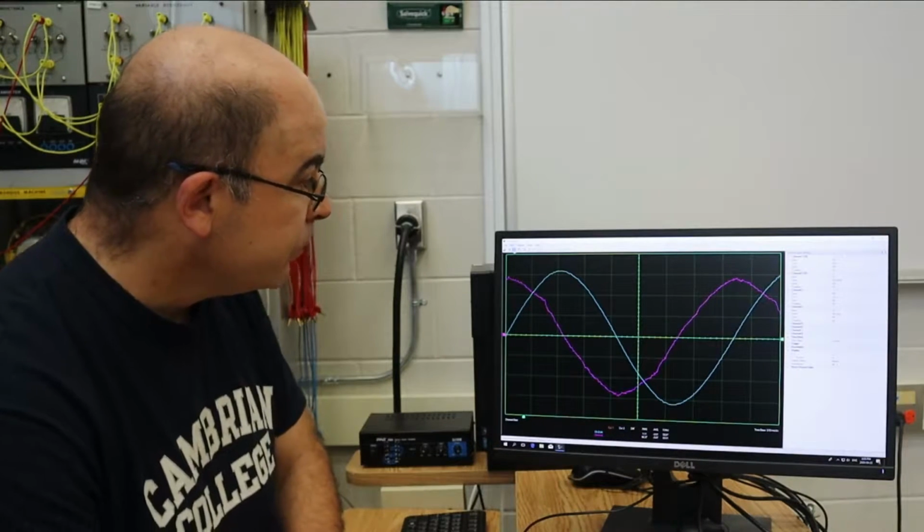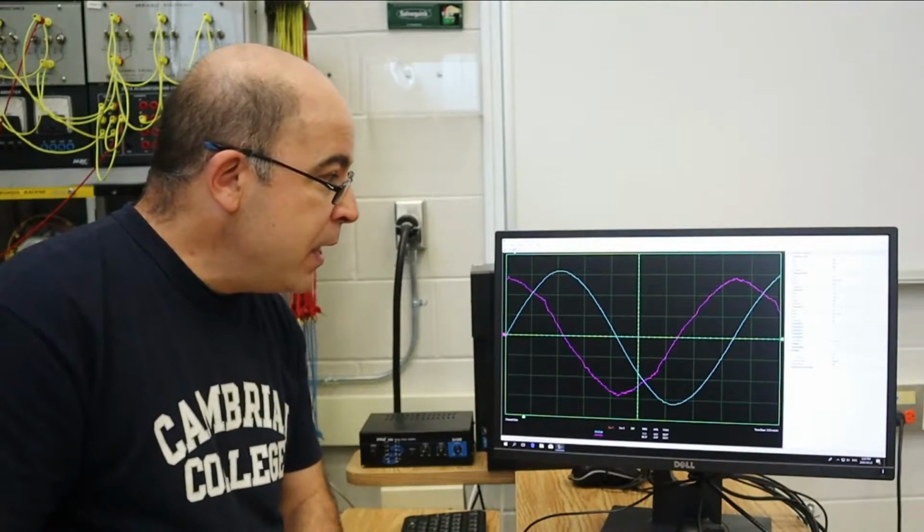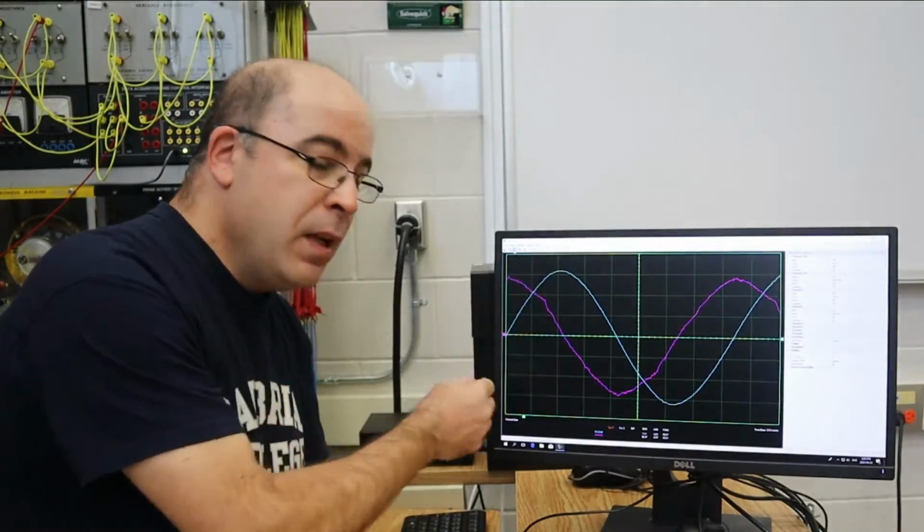Well, that's pretty good. So what do we see? According to our theory, there should be about 90 degrees of phase angle difference between the current waveform and the voltage waveform. Now, in a series circuit, the current waveform is stationary. Because of that fact, we have to say, because this sentence is grammatically correct, that the voltage is going to lead the current, because current can't lead or lag anything. It's stationary, and it is the voltage waveform that changes in relation to the stationary current waveform.